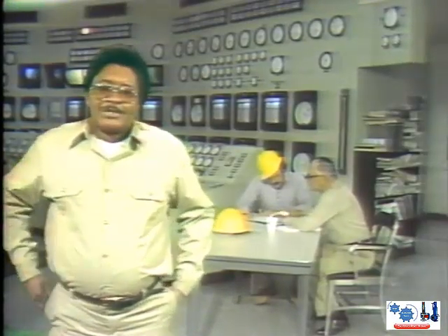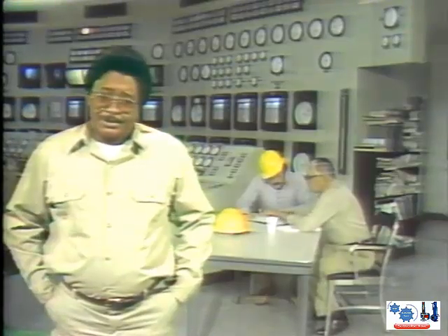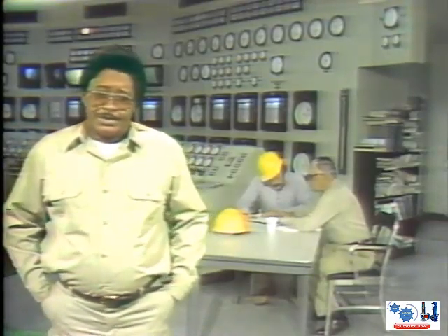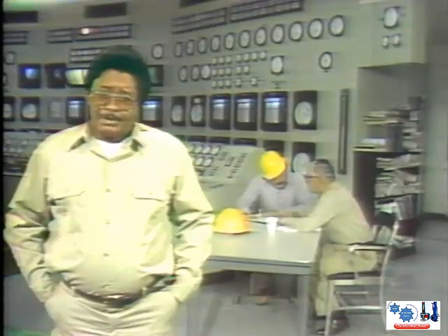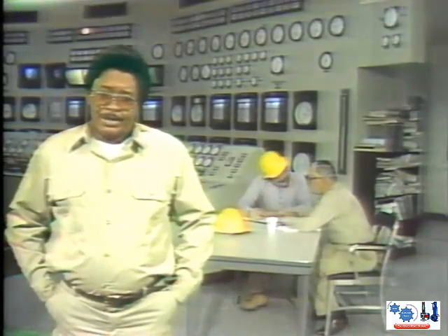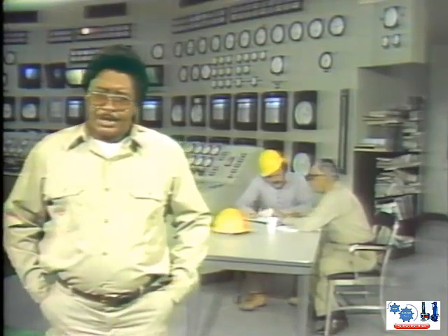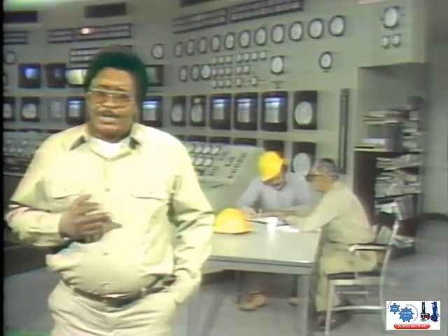Well, one of the best sources that you can use are the steam tables. Traditionally, the steam tables consist of 3 separate tables of information that can give you the values for the properties of saturated water and steam. Table 1 is entitled Saturated Steam Temperature Table. Table 2 is Saturated Steam Pressure Table. And Table 3 is Superheated Steam. In addition to these 3 tables, there is usually additional information available in the steam tables that we'll be discussing later on. For now, we'll concentrate on the information available in Tables 1 and 2.